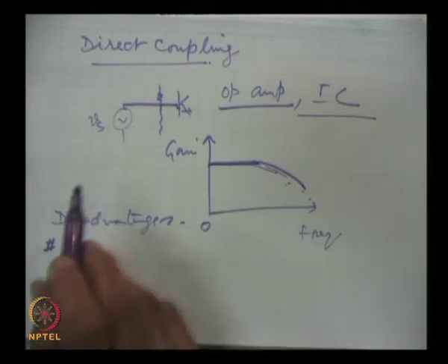If we use RC coupling, then we have seen that the capacitor isolates one stage from the other. The capacitor acts as a block for DC. So we can design the amplifiers more accurately, individually, and then use RC coupling, because for DC purposes the capacitors will keep them isolated. So the biasing and the Q points, the operating points, are not affected.